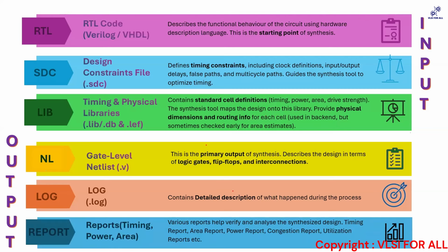The next thing dumped after your complete process is done is your different kinds of reports. Now, the main intention of this SDC file, as I stated, was to constrain your design: how should my timing be, how should my power be, how should my area be. Whether the intention is met or not will be available only when you do the reporting.